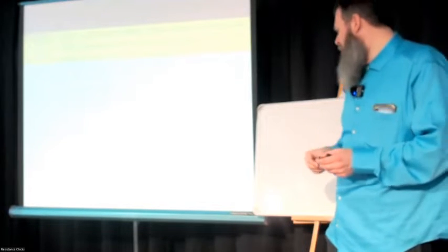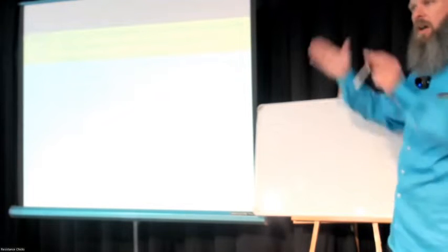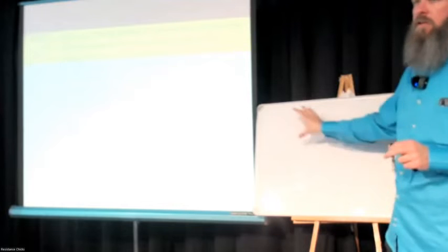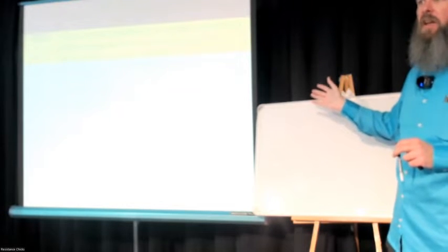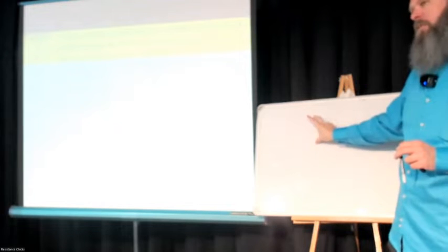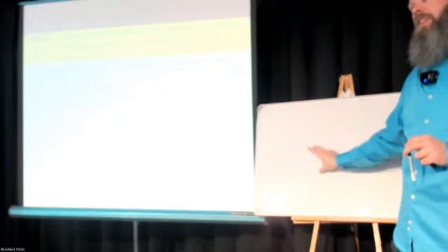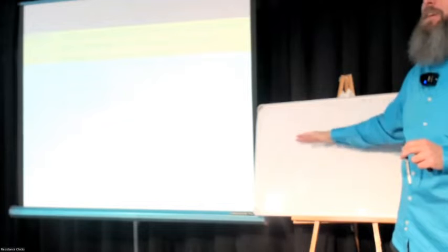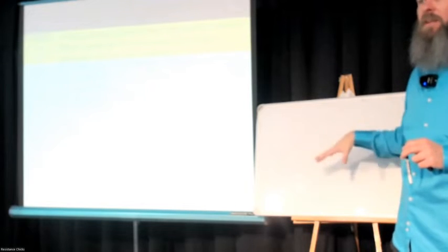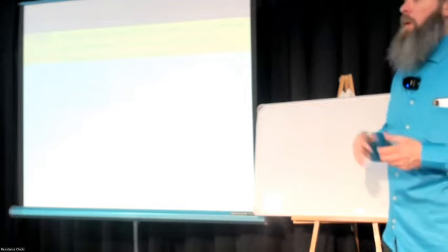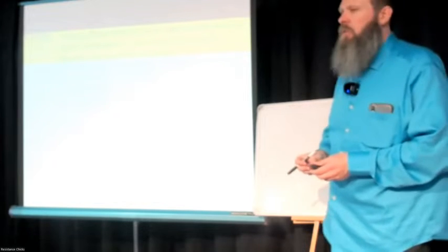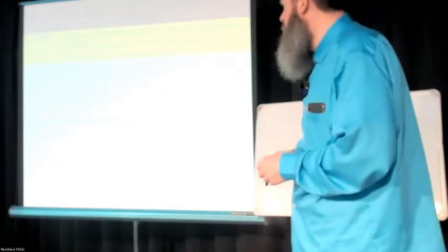And even in addition to that, as I showed with that waveform, we cut off equally at the top and bottom when we made that 2,400 hertz wide. Instead of just doing that, which is the traditional way, you could still leave it 2,400 hertz, but you could slide it down. And so you cut off only the top and you retain everything at the bottom, which could help preserve audio quality. It really is amazing. It's something not possible with old technology. So the new stuff is really cool.